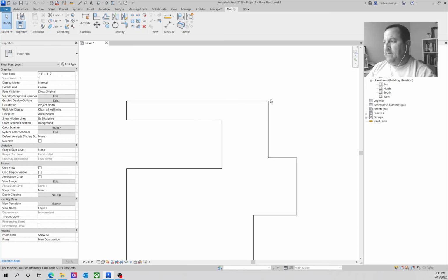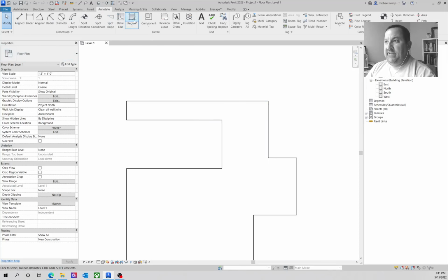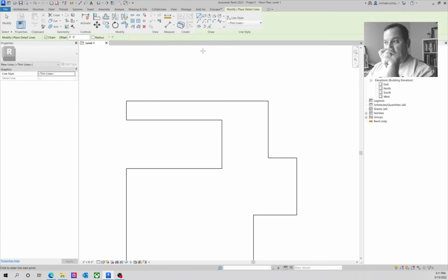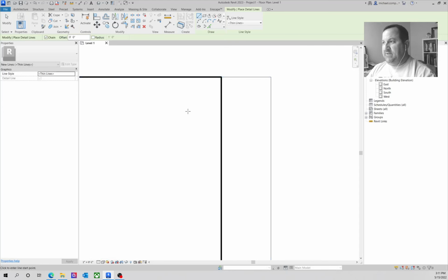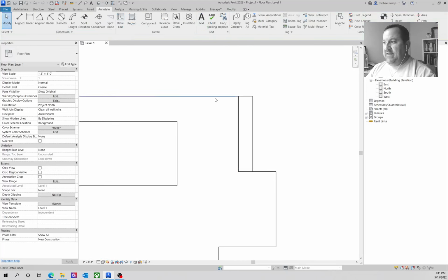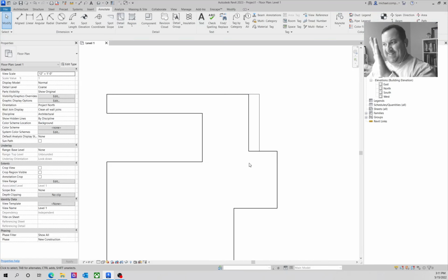So come back here, and we're going to use annotate again, but I'm going to change my pencil from a 4B or 2B to like a 2H. So I'm going to use a thin line, right? And so it's going to come over 1'6", I think is what we said, and then down 8 feet. And hopefully what you see is the line weight difference between those two things. Again, the thing being cut through is thicker, meaning it's closer to the viewer, and the thing beyond is lighter. So that creates depth in a plan.